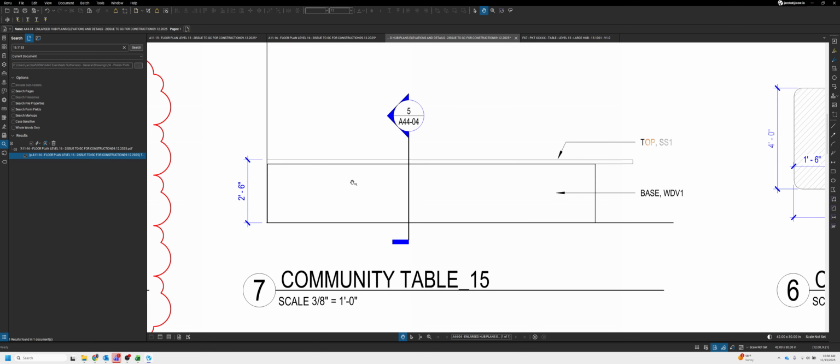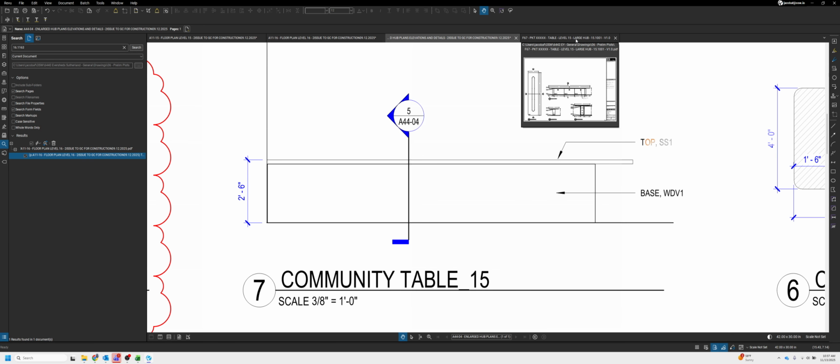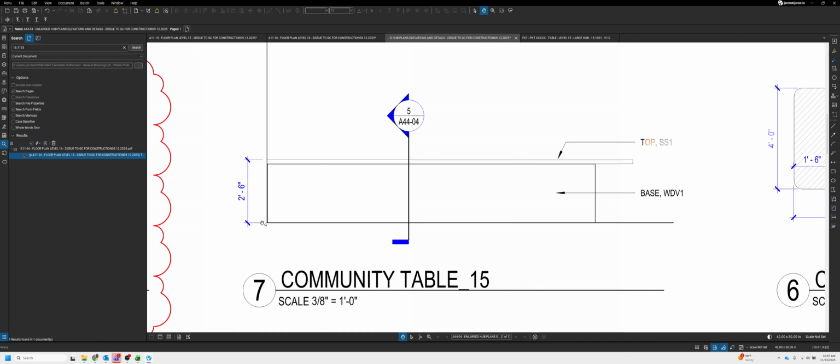General rule of thumb, whenever you're dealing with panels, you don't want to exceed a panel that is 4x8, or 48 by 96 inches. That's just a general rule. Anything larger than that, sometimes it's okay. It depends on the application and getting it through the building, and if the material is available in sizes larger than that. So when we go to draw this, we know that we're not going to be able to draw these panels going all the way across without any breaks in them.